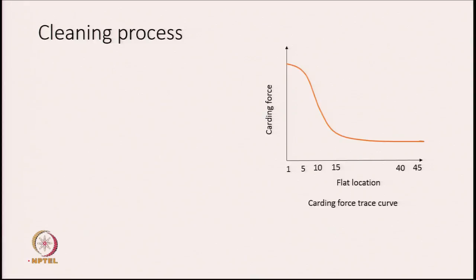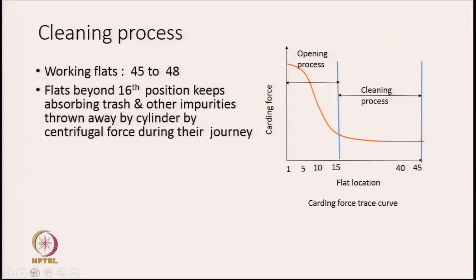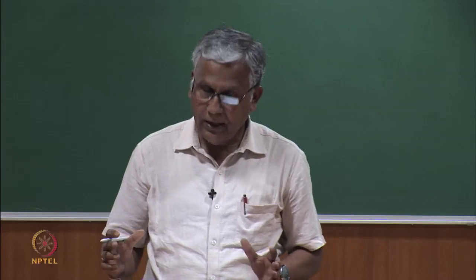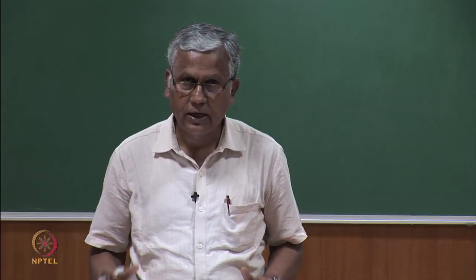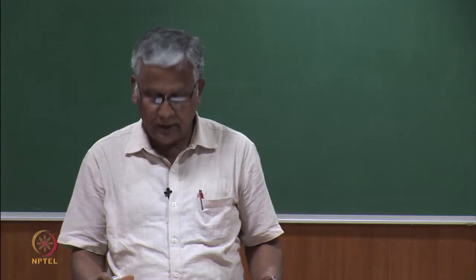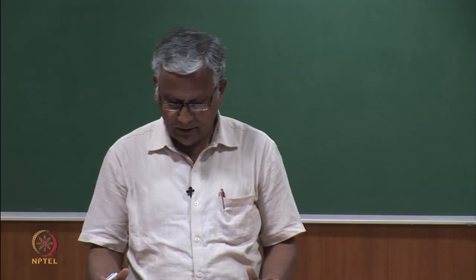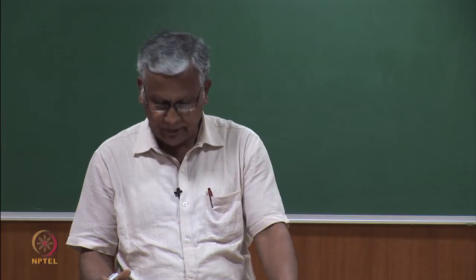How does the cleaning process happen? Beyond the 16th flat location, the flats are completely filled with fibers, they are fully loaded with fibers, and therefore they are not in a position to really open out the tufts, if at all any are left.